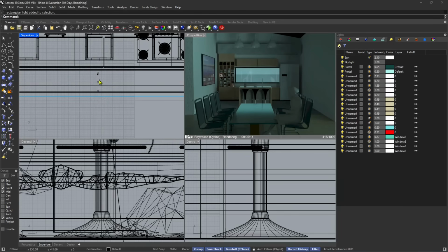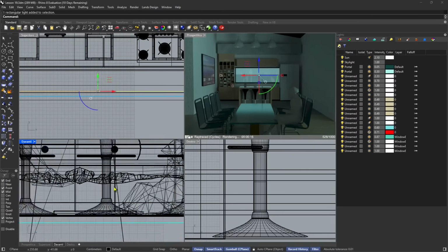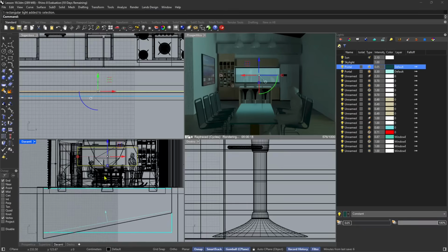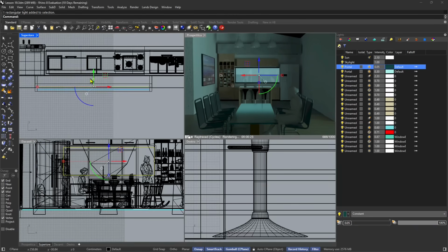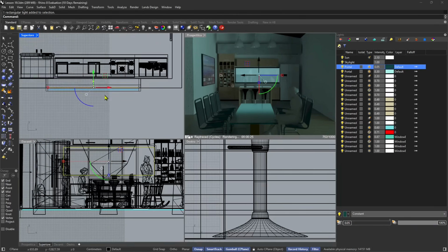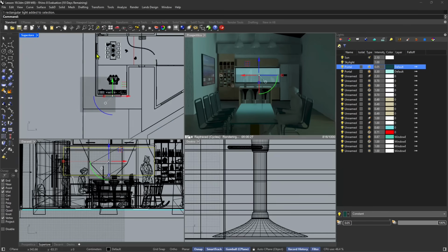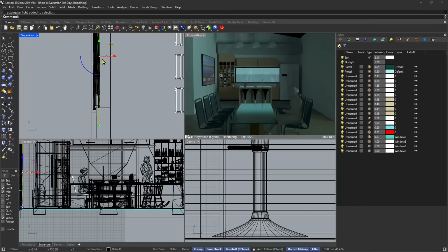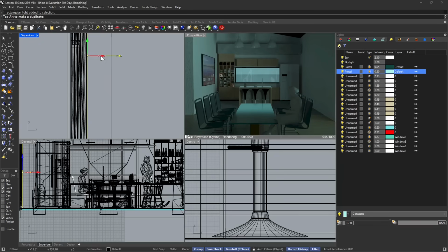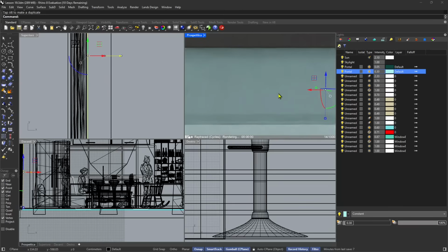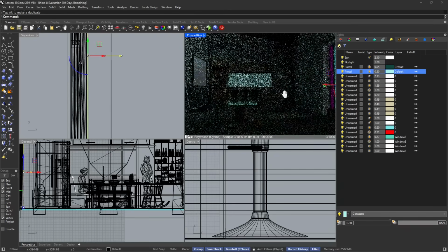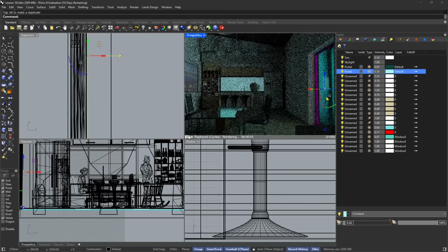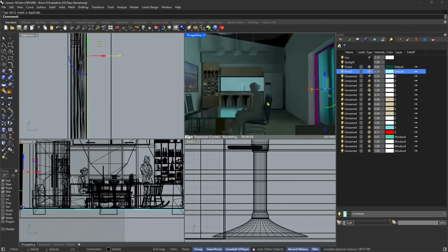It's basically a rectangle light, by the way. So if you see it in another view, it's a rectangle light with the same dimensions as that aperture. And you are supposed to do that for every aperture. So here I have another one. I put another rectangle light, and you can see it here from the side. Also, let's adjust a little bit. There you go. So that's right there. So you can see it's simulating a light coming from the outside.